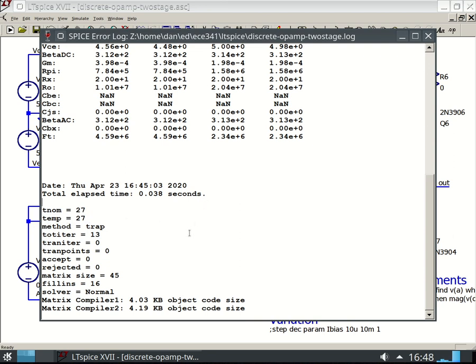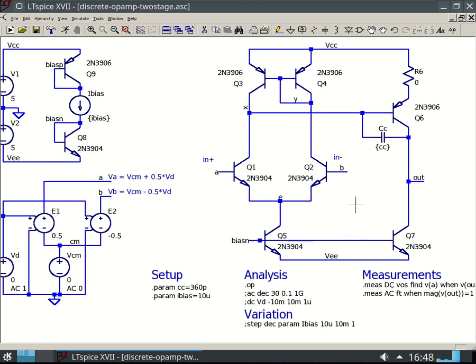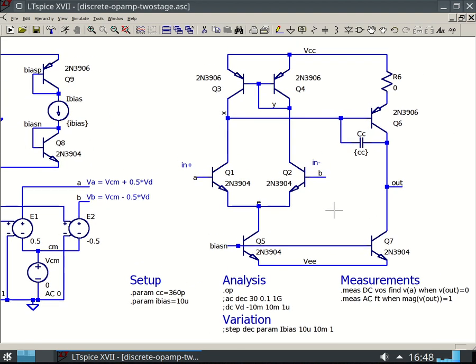So at 27C, our thermal voltage VT is 25.87 millivolts, which you can round up to 26 millivolts, but it's not. LTspice uses 27. PSpice and other simulators sometimes use 25C as the temperature, so watch out for that. Change your temperature with semiconductor stuff, and you know that this is a big deal.